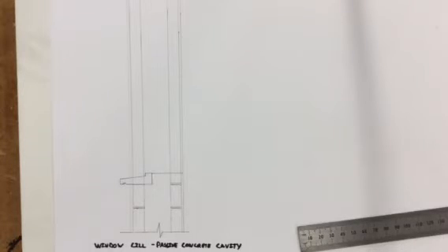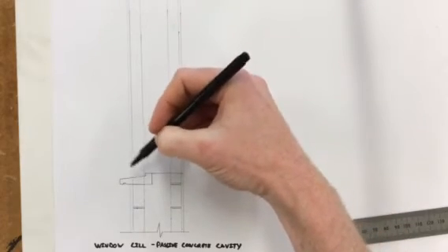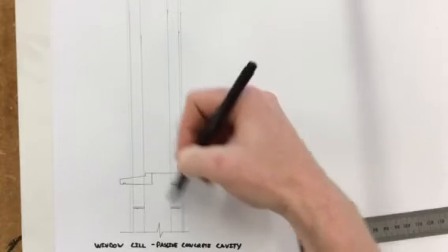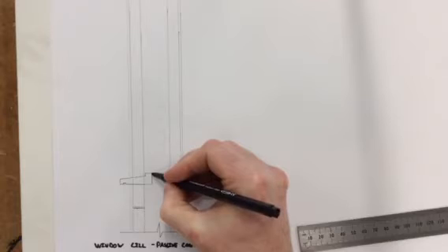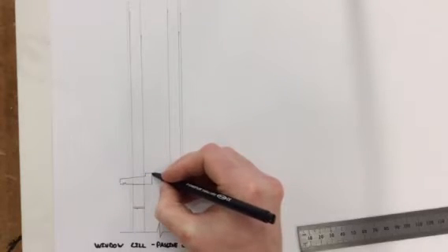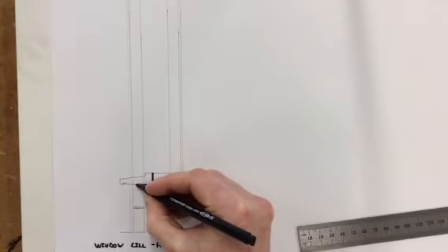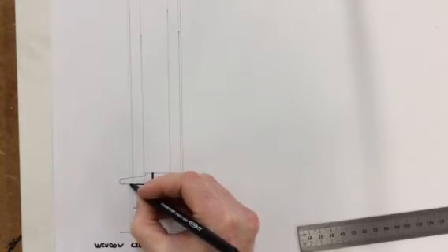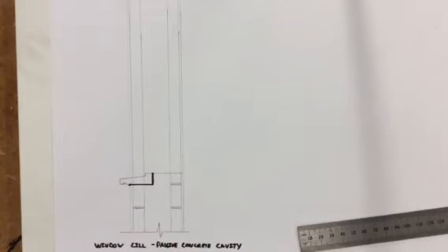A couple of important bits of detail now. If all the rain is coming down here, hitting off the windowsill, the last thing you want is it to penetrate through that, and then it might get into your internal structure. We talked about DPC when we were doing the foundation drawings, the damp proof course. The damp proof course is to be wrapped around the windowsill. It would be wrapped around here, down the back of it, come along underneath, and come out just outside of that, and it just strips down. It just hangs down ever so slightly. So that's your DPC in this.